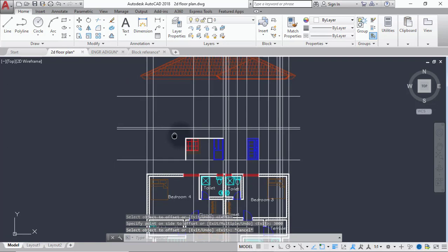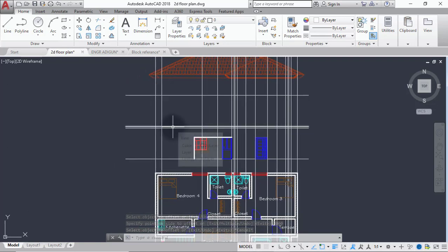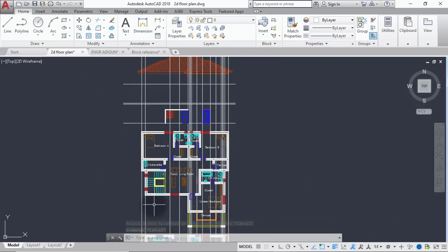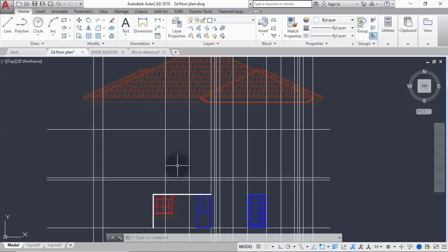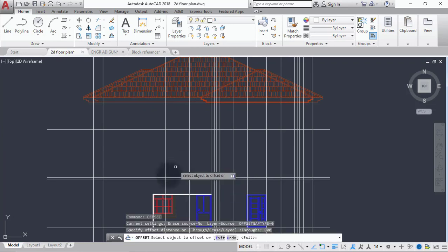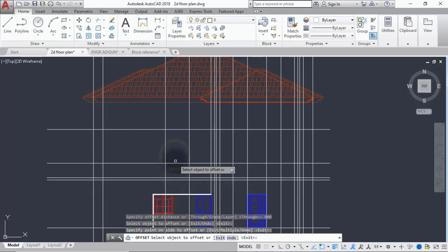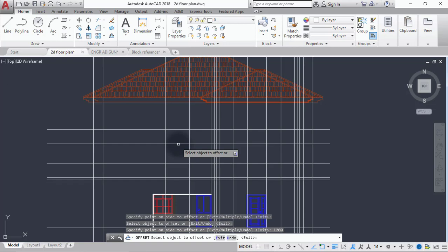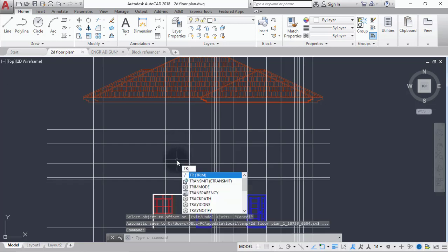So we can continue now. We'll see a wall going up directly from here. So the next thing we are seeing is the window here. So we offset 900 first. After there, your window is starting from this 900 point now. The window is having a height of 1.2, sorry, and we'll trim away the unnecessary.